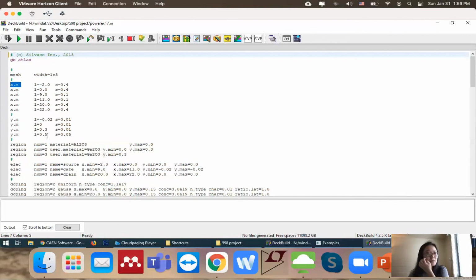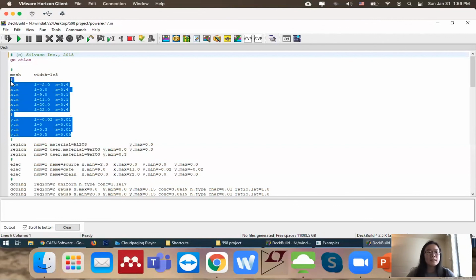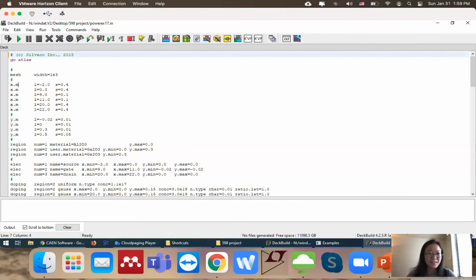But if you do not fill the mesh with the device, you're going to get an error when you run the code. So what I typically suggest is that you give the empty area, where the device is not, some material: you can assign that area as air or silicon nitride as passivation. Just make sure to fill all the mesh you're assigning here, it is very important. Yeah, so now let's understand what this code means.